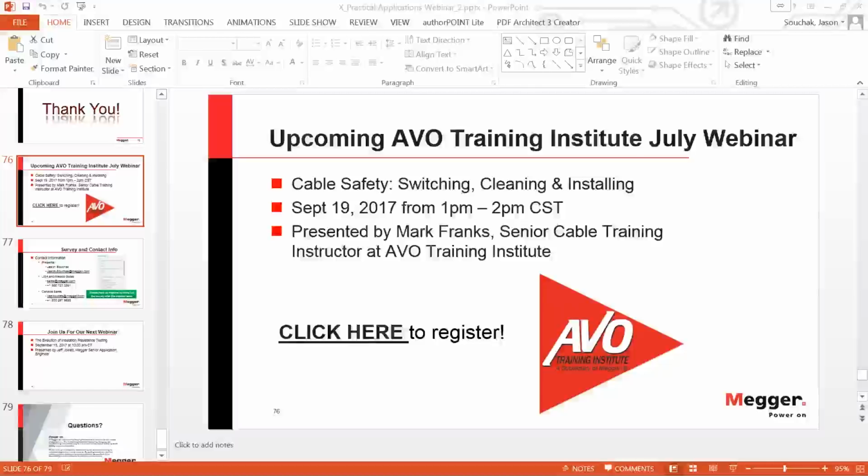Whenever you have to do fault locating, it's nice to know where the splices are in the cable. Or when you do PD testing later on, it's also very nice to know where the splices are. Whatever you can do up front to define the cable might be helpful over the life of the cable, which could be 40, 50 years, right?